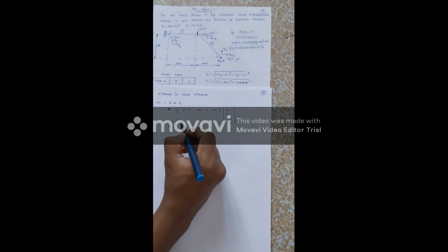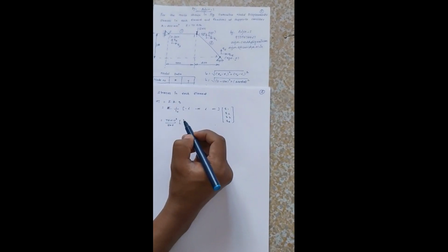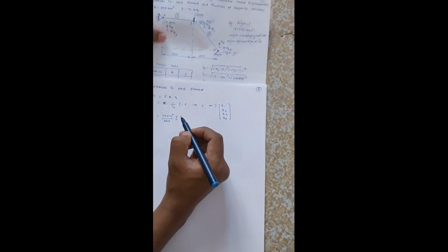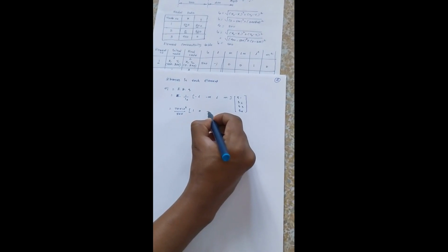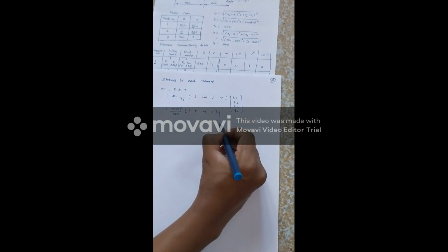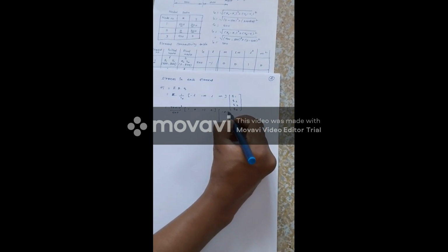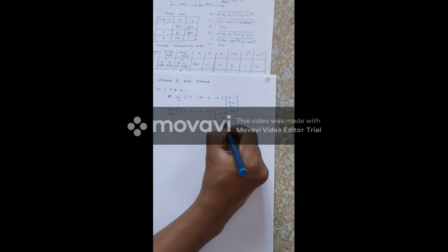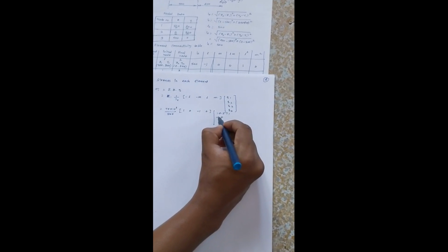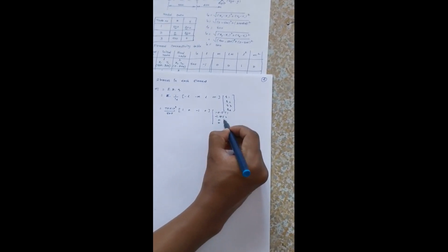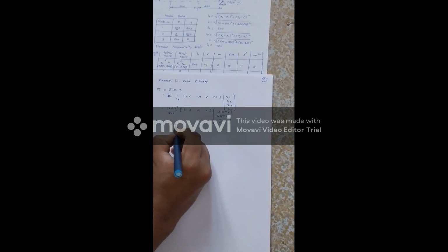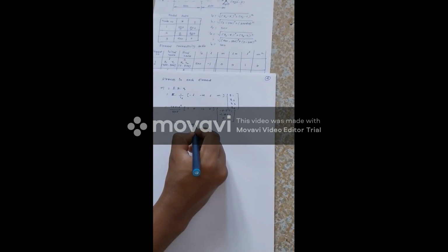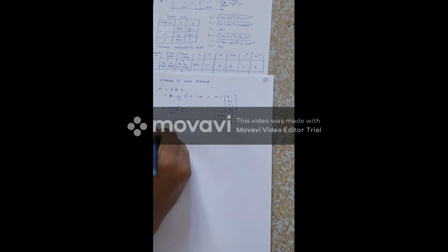So the direction cosine for element 1, L is minus 1, so minus into minus becomes plus 1, M is 0, so this becomes minus 1, 0, and the value of Q1 is minus 0.571, Q2 is minus 1.952, Q3 is 0, Q4 is 0. If we simplify this, the value of sigma 1, that is the stress for element 1, will be minus 79.94 Newton per mm square. This is the stress obtained in element 1.